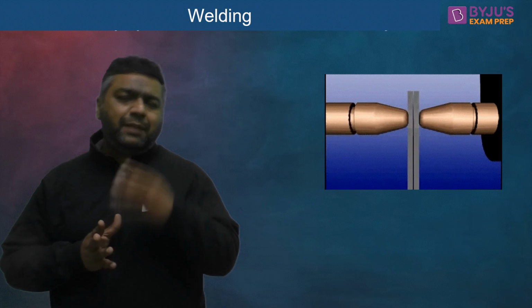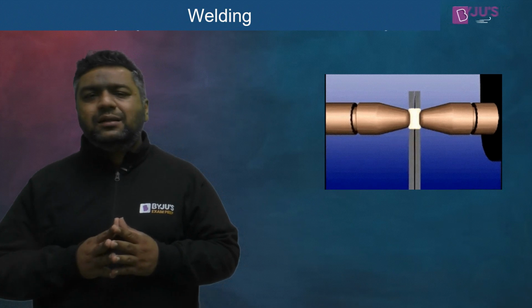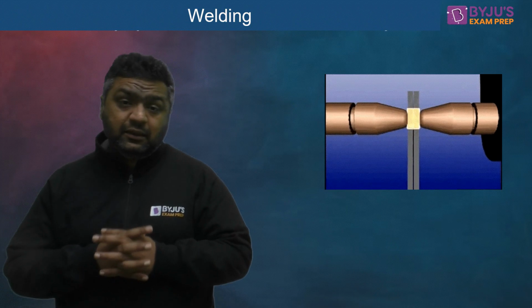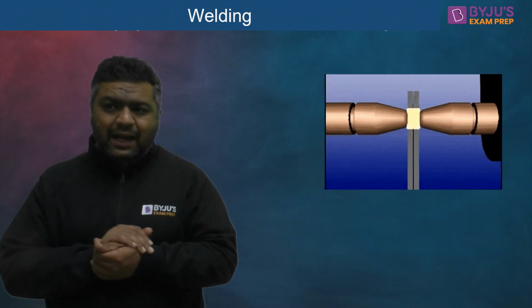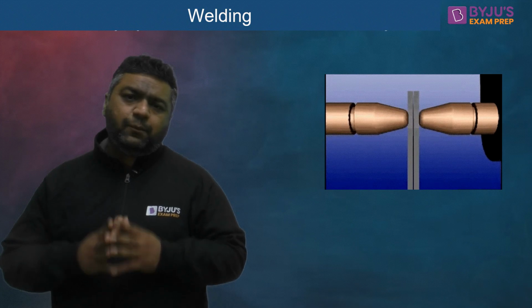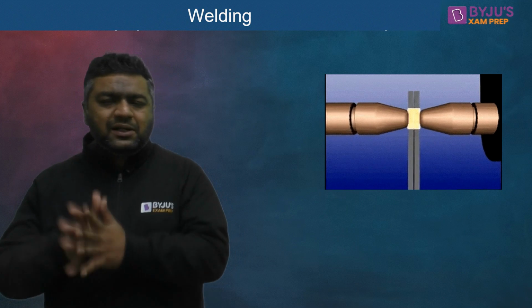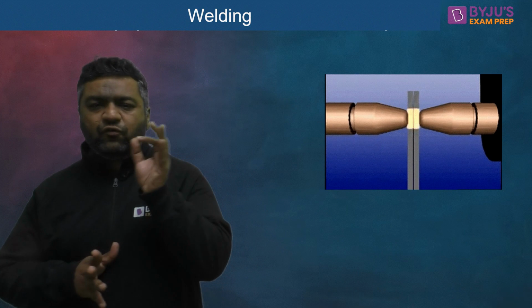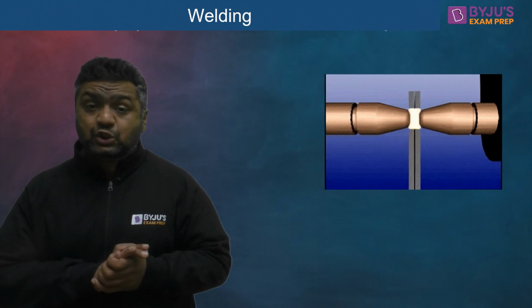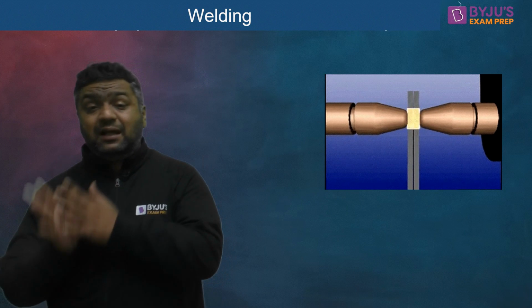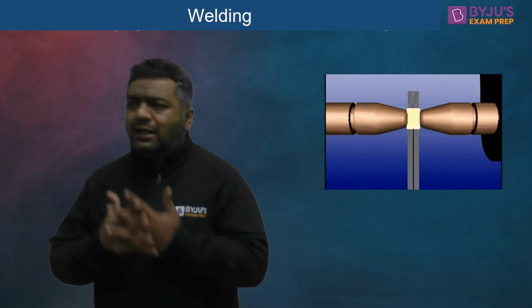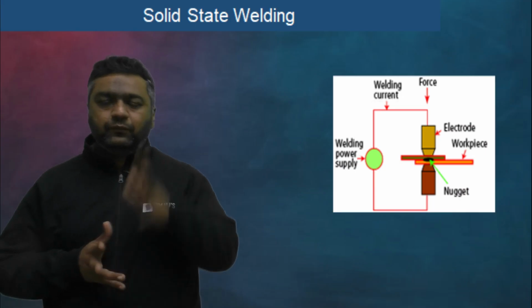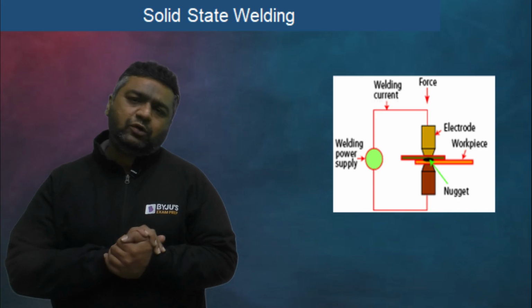So from there metal starts melting, and that fusion zone is increasing up to the electrodes, and generally any shape can be possible for the fusion zone. It is similar to the weld bead, but in resistance welding we are giving the name of weld nugget in place of weld bead. And guys, for the calculation purpose, we generally assume those nugget to be either cylindrical or spherical, otherwise shape can be any. So this was the spot welding process.